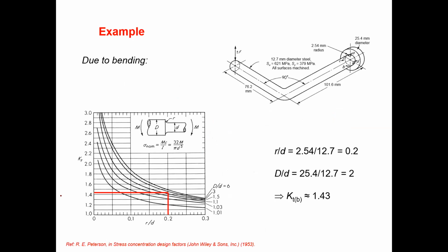So bending and torsion and axial, three loading types, we assume there is another assumption. We assume they act independently. So we can use the superposition theory. Okay, that means we can calculate each and everything separately and combine later. So due to the bending part you can do that, then due to the torsional part, and if there is an axial part, due to the axial part you can calculate separately, and later on you can combine.